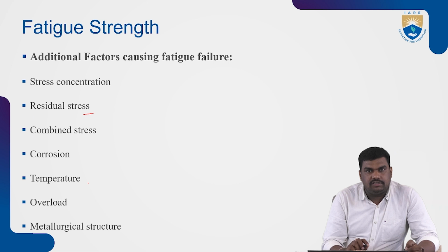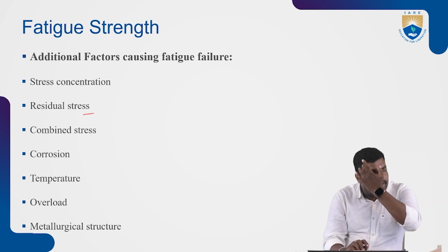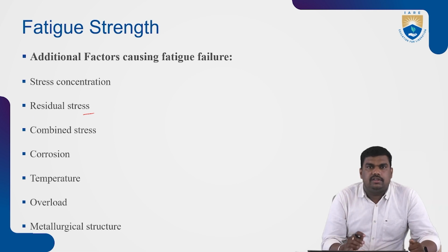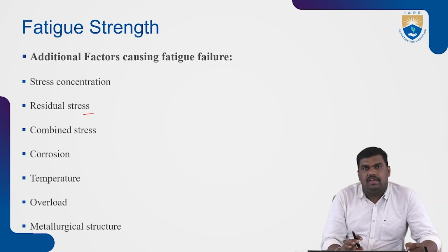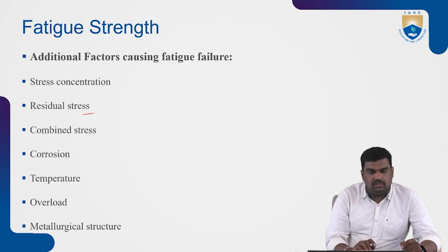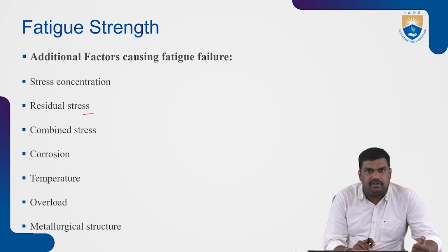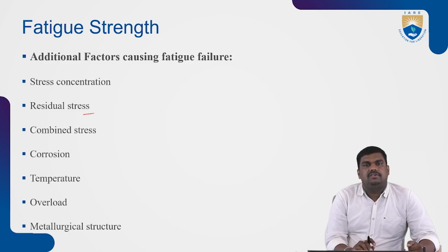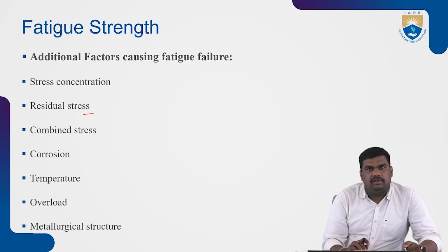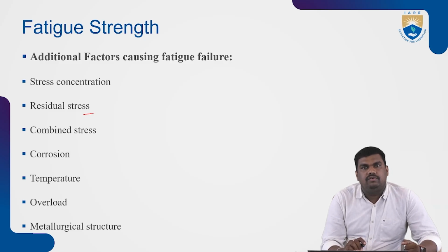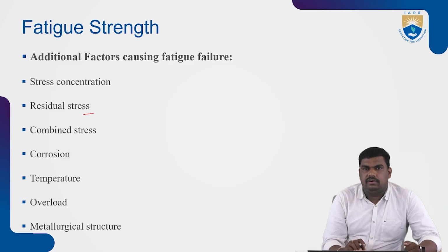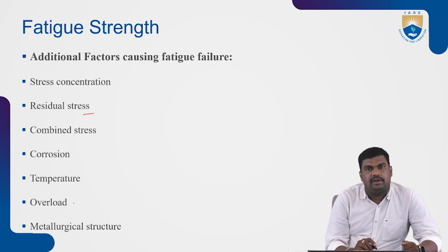Then temperature effect, when the material component is working in low temperature condition or high temperature condition. Materials always react with the temperature. So sometimes the ductile to brittle transition temperature also will happen, so ductile material will be converted into brittle material. Then when there is overload, the load is more, then due to that high load, the failure will occur, right? And the next condition is overload.